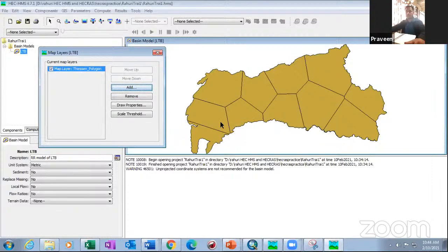Here what I'm assuming is that each and every Thiessen polygon has one gauging station. That's very important, because I have considered the influence of each gauging station, and when I create a subbasin within that, I'll have very little error from area which is not contributing.